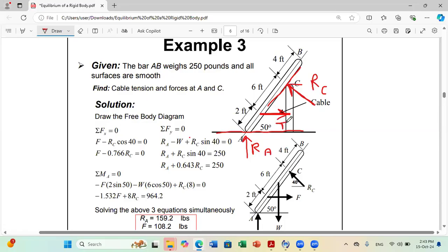So I have three unknowns in this problem, and I want to solve for them. So of course, I need to write three equations of equilibrium. My three equations of equilibrium are sum of x equals 0, sum of y equals 0, and sum of moment about any point that I select equal to 0. I can start first with sum of x equals 0. To be able to project RC on x, I need...